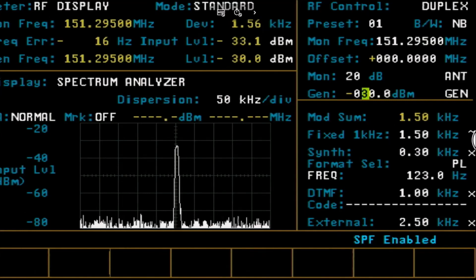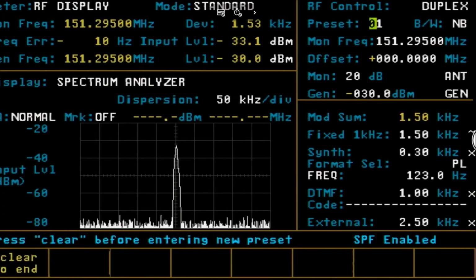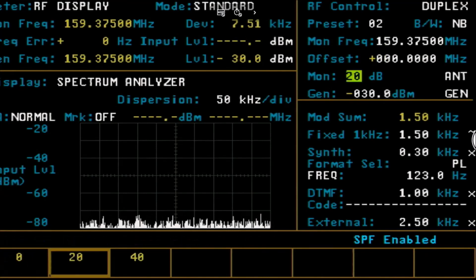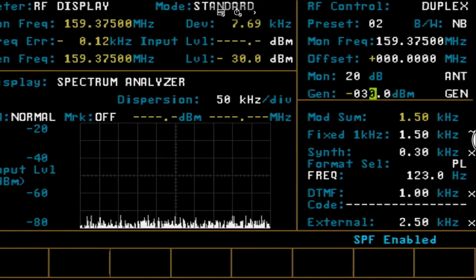And we'll go ahead and flip the frequencies again, and now we should see a complete drop away and once again go down and turn my level all the way up to 0, and you still can't see anything. So we're completely notched there, and that's a good duplexer in both directions.